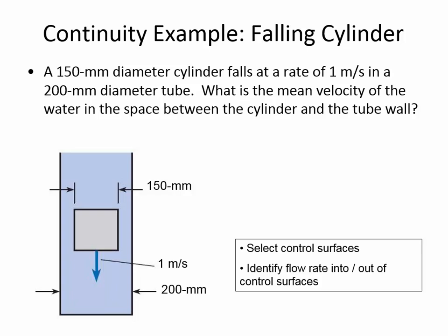How do you get from Q to knowing what the velocity of the jet coming out of the nozzle is? Right. So V is Q divided by area. I just told you that the diameter of the jet is 8 millimeters. So you don't know the jet area directly, but you know it's pi d squared divided by 4, and the diameter is 8 millimeters. So it all fits together. With your stopwatch and the viewing tube, you're going to be able to quantify volumetric flow rate, and the cross-sectional area you calculate from the known jet diameter.